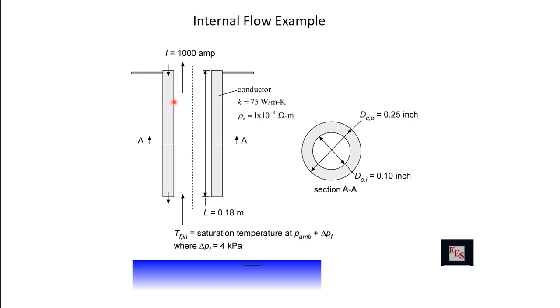In that kind of an arrangement, what you do is you actually run vapor through channels in the lead. So here's a situation where we have a current lead that's in the shape of a cylinder. The current is flowing through the wall of the cylinder. The wall is actually, this isn't to scale, obviously this wall is pretty thick. The current lead is actually more material than it is channel if you look at these dimensions. So here's my cylinder that forms the current lead, and the vapor flows through the center, and that vapor is going to help cool the current lead and keep it from getting too hot.